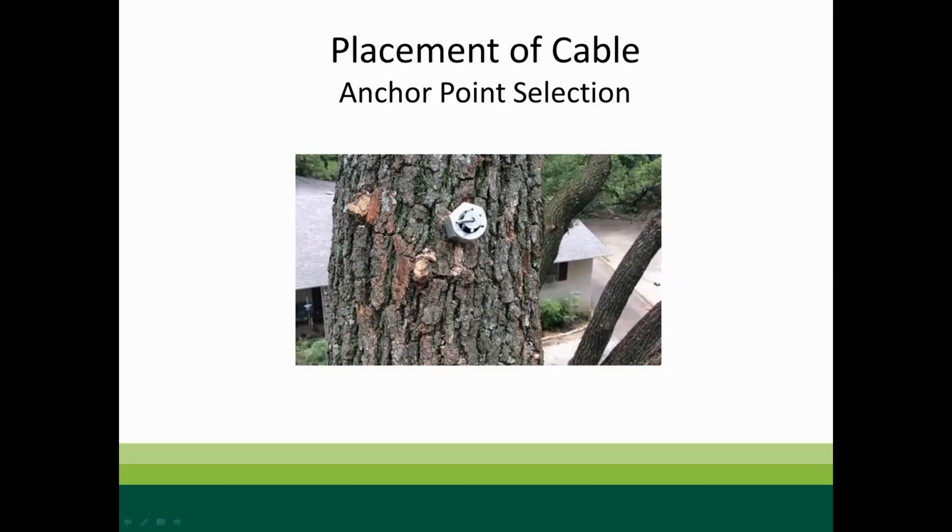I got a quick question. If you leave the dynamic cable in when it's tight, isn't that kind of like a death sentence for that lead that you wrapped around? Yeah, that's what I'm saying. Dynamic is a totally different ballgame. You would want to take that out, and you'd want to pre-tension everything on the tree first.